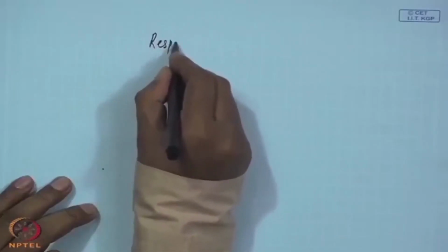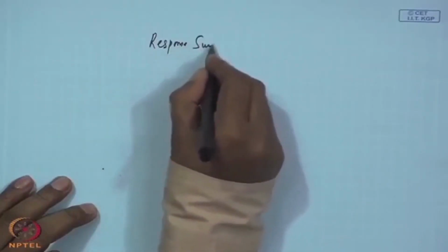Hardness cannot be controlled because it will be controlled by the centrifugal casting shop, not here. So we have control, and you can improve the backlash. This is one step, but it requires further optimization, what the process setting points will be. That can be found out by statistical optimization using response surface methodology.